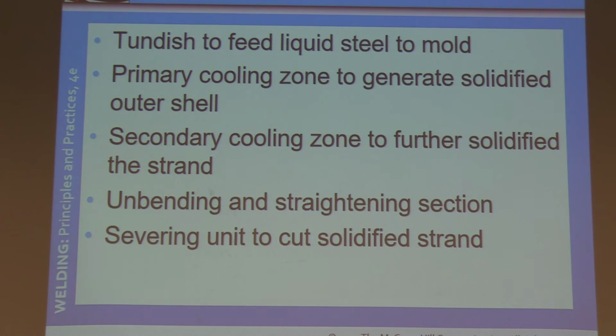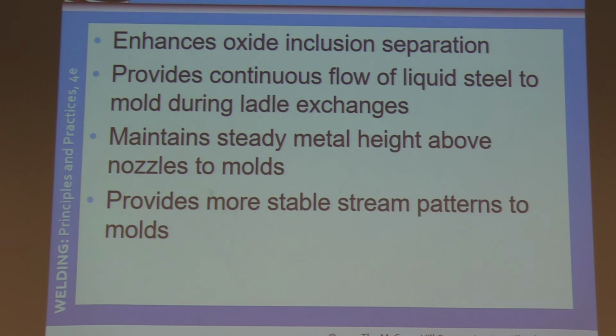To give the inside a chance to become solid and still keep the outside from cooling off too much, the ingot is lowered into a furnace called a soaking pit, which heats the steel for rolling. Figure 3-27 on your right-hand page illustrates the processes used in solidifying steel.